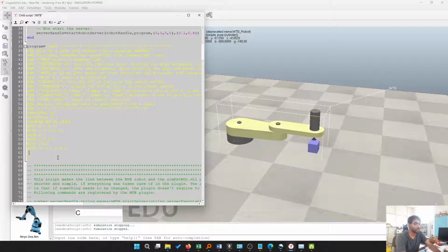See, clear bit 1. What we'll observe now is that the robot will go to the home position, extend the actuator below, and then grip. Then it will move back to the home position, retract the linear actuator, then go to the right-hand side and release the gripper. That's all the code is written, right?